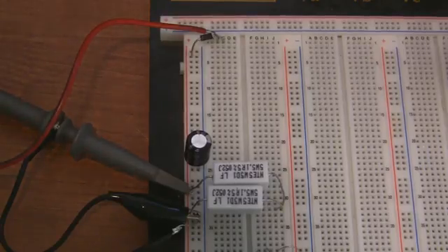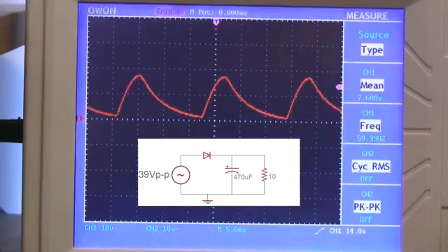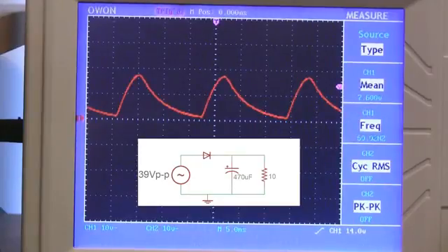Okay, let's turn it up a notch. With a 10 ohm load, this circuit should draw a lot more current. Well, that sucks. Now we're back to the situation where the voltage is sagging in every cycle. The average voltage is 8 volts, so we're only drawing about 0.8 amps, and the magnitude of the voltage ripple is just huge. Imagine trying to power something with this. The voltage would constantly drop so low, it would never even stay on. So even 470 microfarads is just not cutting it anymore as an energy reservoir.